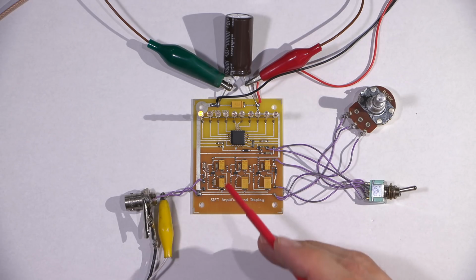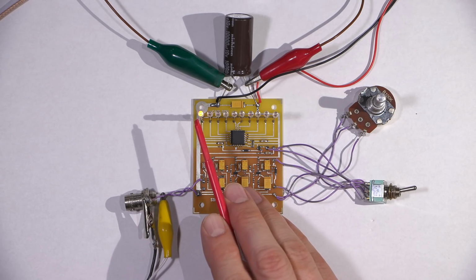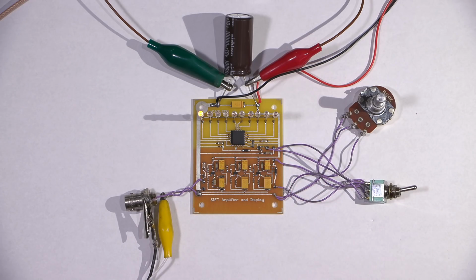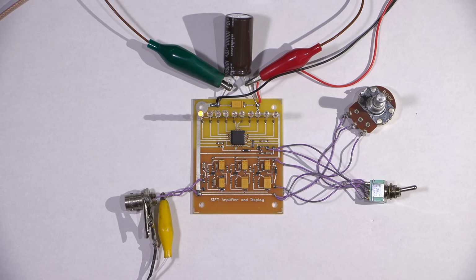Now, I will tell you this. This amplifier is so incredibly sensitive that it's running within the sensitivity of a standard radio receiver. For example, in order to take this light display and bring it right to the top here, it takes under 50 microvolts. Many radios that I've aligned in the past have specs to align it for 85 microvolts for S9. So that's 85 microvolts of signal fed into the input jack to give an S9 signal, which is almost a full display on some of the smaller radios.